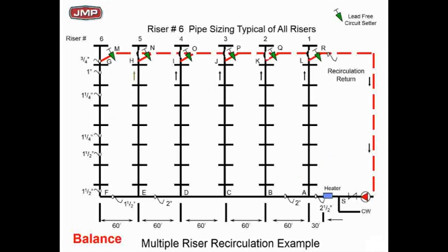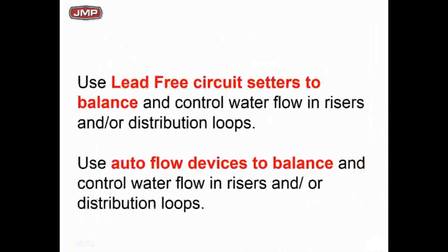But if you do that, then what would you have to do here? 1, 2, you got what, 6 risers. You have to make sure you oversize your recirc pump to pump about 3 GPM to make sure you got enough flow rate so each one of those things will work. I see a lot of engineers doing that: they're putting flow limiters in each riser and taking that minimum flow rate to make that flow work, and they're oversizing their recirc pump to make sure they got enough flow to make it work. So making it self-balanced. And making them self-balanced with a little flow limiter makes a lot of sense.